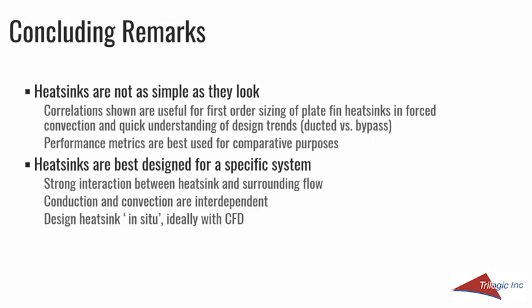My recommendation: design the heatsink in situ, ideally with CFD. Do some initial sizing, like, hey, can we cool this component with this much space? Correlations would be great for that, I think. Yeah, it looks like we could do that. In terms of designing that, I would use CFD. And in terms of validating the design, certainly you want to use measurement.